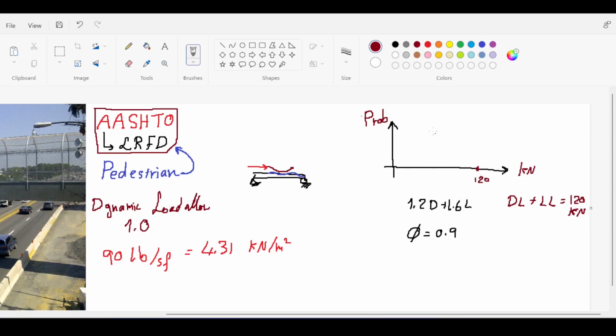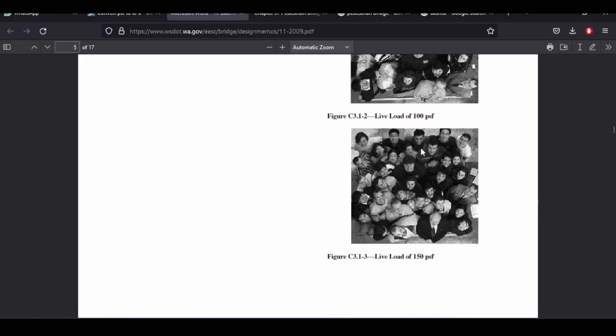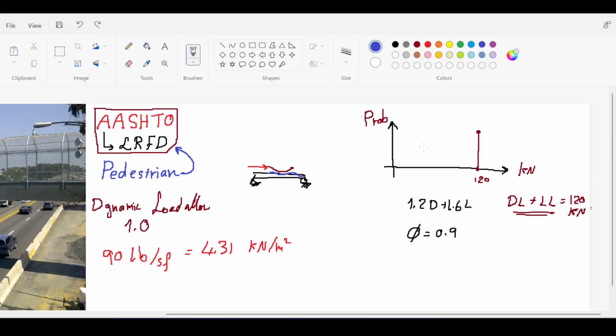Of course, the probability of this happening is quite high because what you calculate here is actually the average of something called the natural distribution of loads. Because you are predicting, on average, something dead load and something live load. Now, this is incorrect because there is variation in dead load, because you don't know exactly for sure what the thickness of a slab is. And there is a variation in live load because the only thing you can do is predict the live load, although you don't know how the people will react.